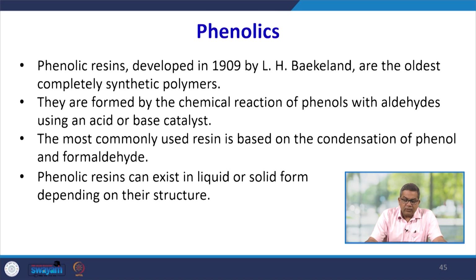Now, let us talk about the phenolics. The phenolic resin was first developed by Baekeland in 1909, and they are the oldest completely synthetic polymers. They are formed by the chemical reaction of phenol with aldehydes using an acid or base catalyst.